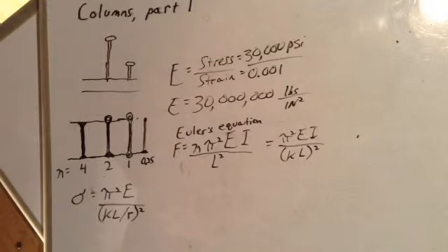Okay, you may remember in our gyroscopic precession lesson how we determined that the radius of gyration of a disk was about 0.707 times the radius of the disk. A disk like a millstone or a big old cheesecake or something like that. But the radius of gyration of a ring was equal to the radius of the ring, because all the mass of the ring is out there where the ring is. There's nothing but air inside it. Whereas a big old cheesecake dish has cheesecake all the way from the outer edge to the center of the cheesecake.